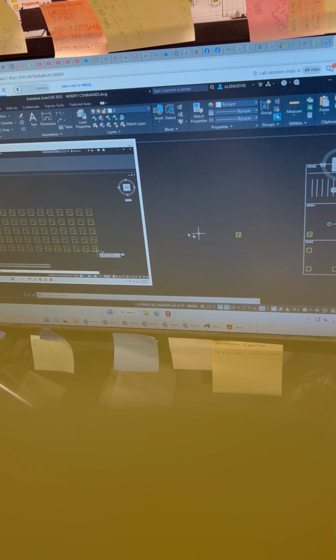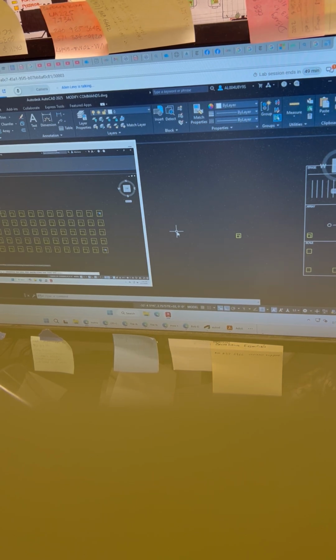Look at the shapes of these ones. These are arrows. What that means is I can adjust how many rows and columns there are by just gripping these grips. Go ahead and click on this triangle here at the end and move your mouse, and look how you can dynamically add columns and rows. See that?